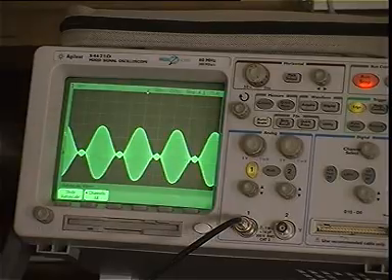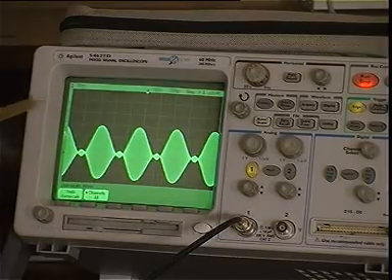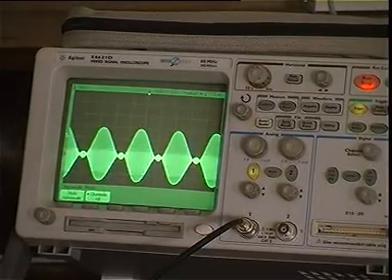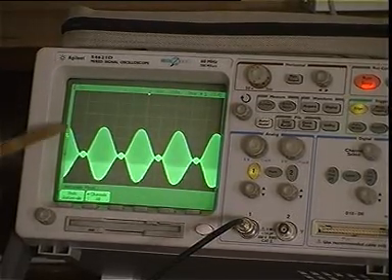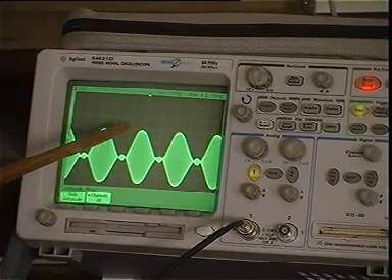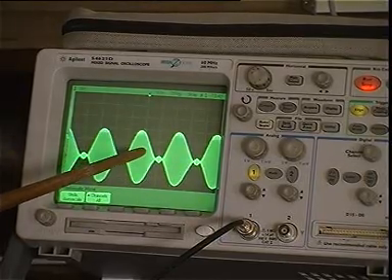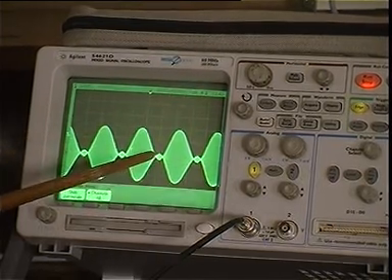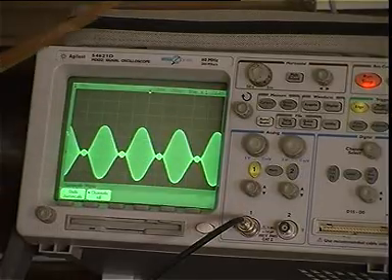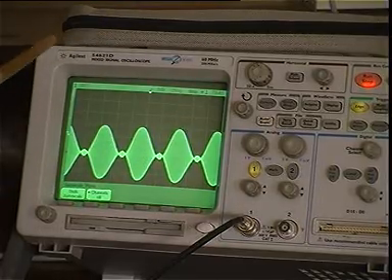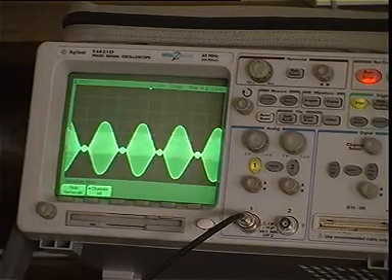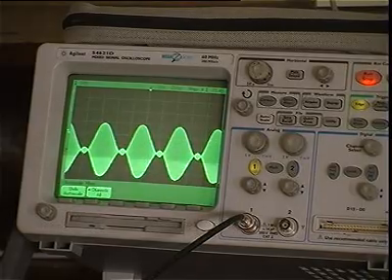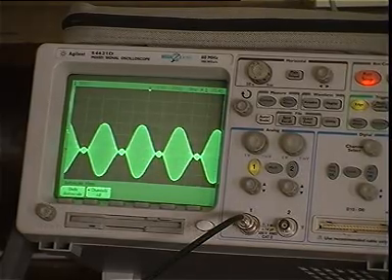If I set mu greater than 1, what will happen? When I am trying to detect it, I am not going to get exactly the same waveform as it was at the transmitting side. There is a slight distortion here. The envelope detector is going to trace the envelope, but it's not going to generate the actual waveform. There is a slight distortion here because mu is greater than 1. So we do not want a situation where mu is greater than 1, because it would lead to distortion. I will not be able to recover the original signal that I transmitted. So we always keep mu less than or equal to 1, so that I can recover the original signal.